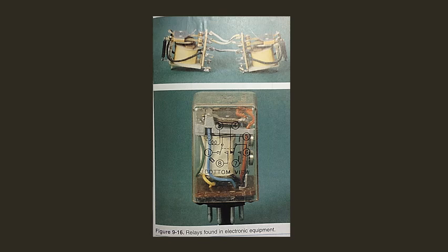In addition, relays are designed with coils that work on direct current or alternating current. You cannot energize a DC coil with an AC voltage, or an AC designed coil with a DC voltage. Doing this may result in an electrical fire. A detailed explanation of these principles is found in Chapter 14, dealing with inductive reactance.